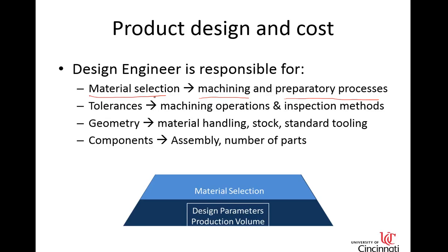One that a lot of people, I found when I was in industry, don't really take into account is something like tolerances. Tolerances can have a major impact on the cost of a product. A lot of times engineers will design something and give it a tolerance just based on the previous design, without considering that by picking a very restrictive tolerance, they have just dictated a certain type of manufacturing process. Not all manufacturing processes have the same level of capability.